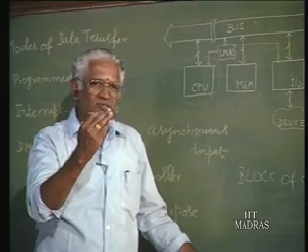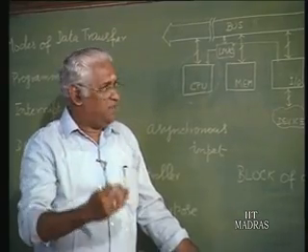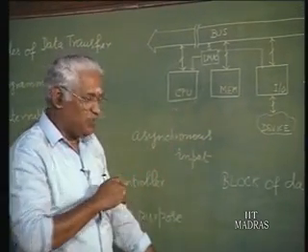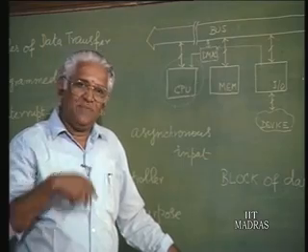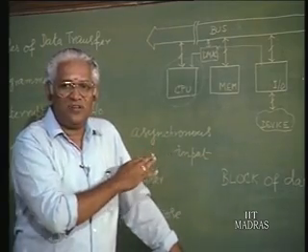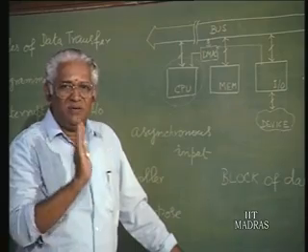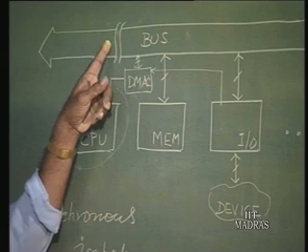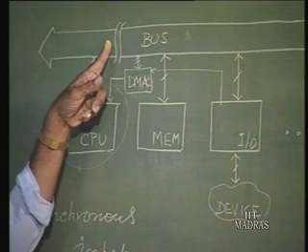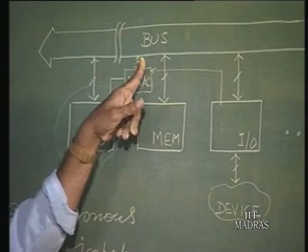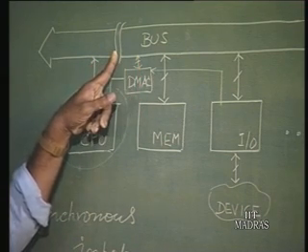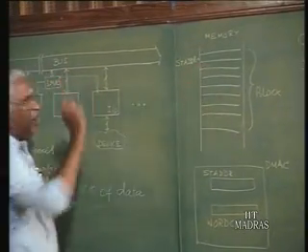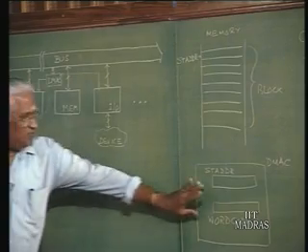The device will request a DMA transfer. When it requests, immediately as far as possible, we will see when exactly. We had talked earlier about when the interrupt comes and when the interrupt is acknowledged. Similarly, here we have to discuss when the DMA request comes and when the DMA request is acknowledged. As soon as the CPU relinquishes the bus, that is releases the bus for the DMA activity, the DMA controller should know from which address and how much data. So, these will be part of this.